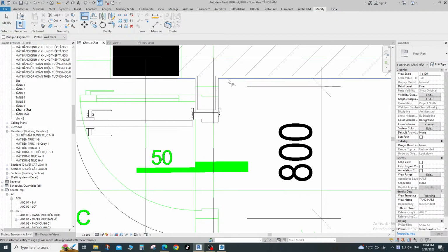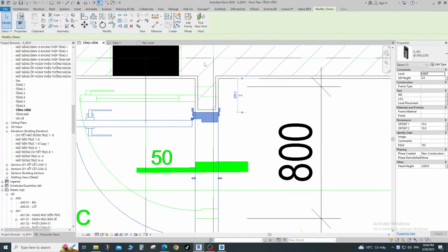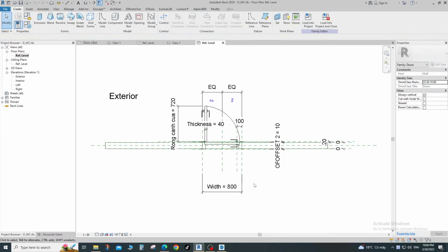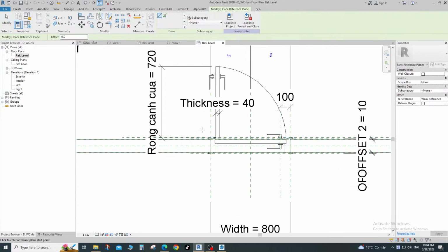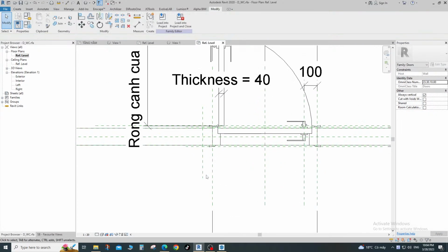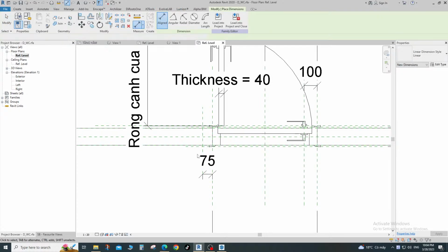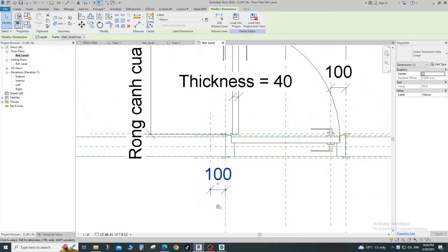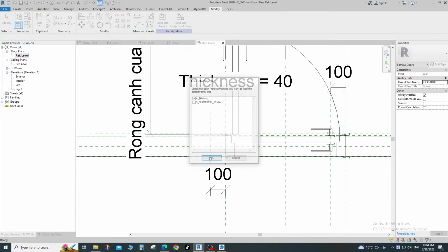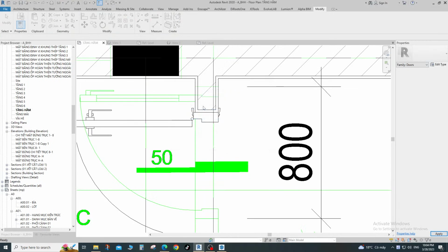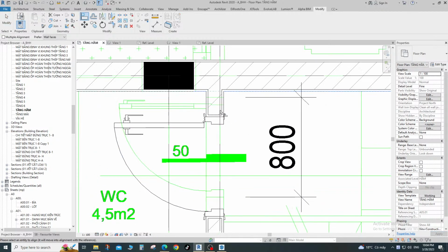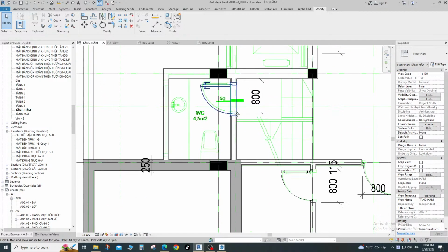So just check how many. You can see from ground floor to level 2, we need 43. Okay, and then there's one floor, a landing, another landing up there. So probably roughly divide by 4, which is just make it 11. So 11 riser, and then just move your cursor down roughly a meter. You can see that there's a dimension there. So roughly go down.